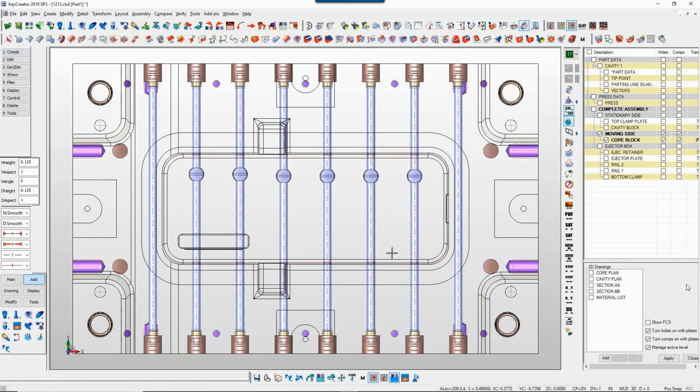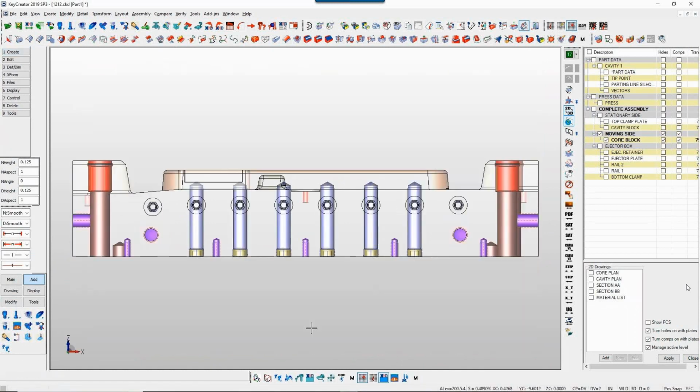And this is what's really cool, is when you take a look at these baffles, the lengths are 100% automatically taken care of. So think about it. Single click, put it in position, automatically centered it to the water line. It knows to snap to the water line automatically. And then the length is completely 100% figured out for me, and the material is up to date accordingly.